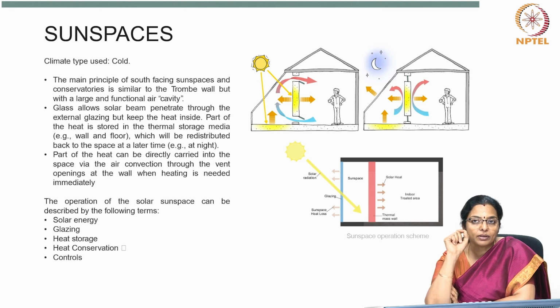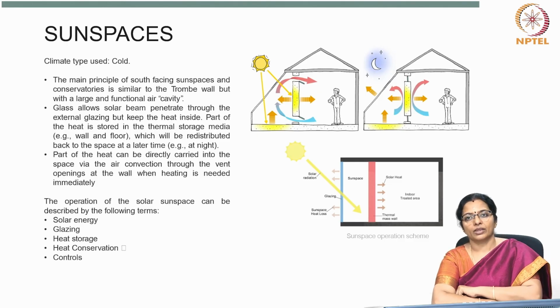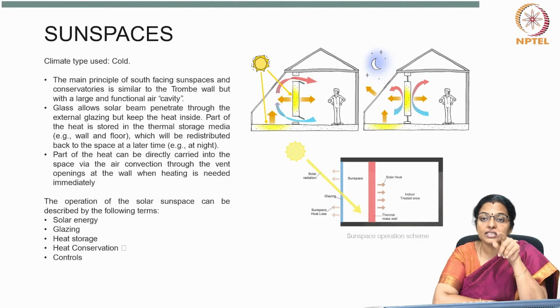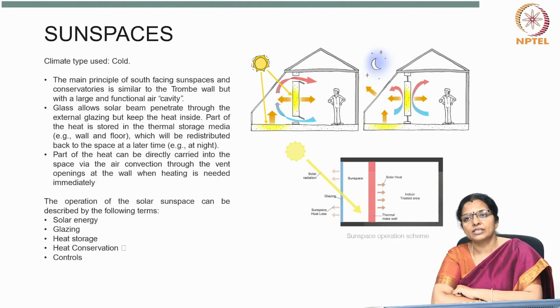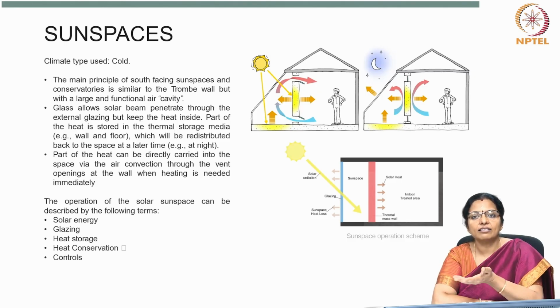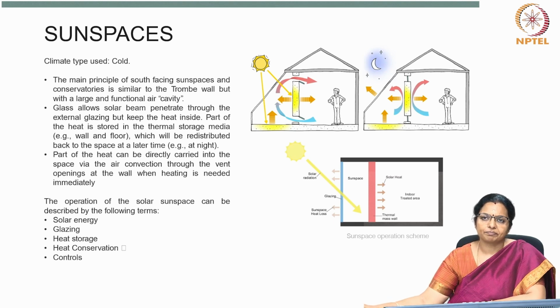Orientation must be proper. So, in order to achieve optimization in design, the glazing has to be perpendicular to the radiation received at any time. Heat storage: the first phase of the heat storage procedure is the solar radiation absorption. The surface color and texture are the two main parameters that affect the absorptance. Dark colored surfaces are generally higher in absorption compared to light colored.